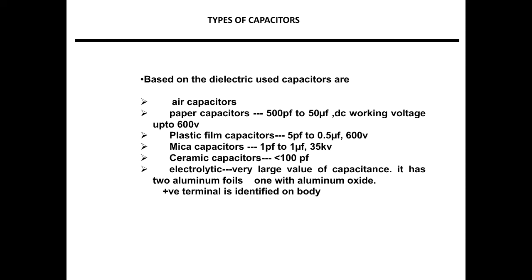When connecting an electrolytic capacitor, it's very important to remember that if we connect the polarities reversely, there may be a chance of explosion. So electrolytic capacitors have to be connected in correct polarity, and for that, the positive terminal is identified on the body of the capacitor.